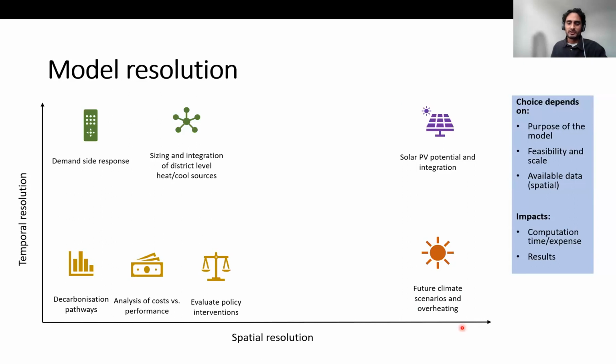They'd both be sensitive to building specific geometry. They'd be sensitive to the building orientation and also the surrounding context. So the shading would make a big impact for both of these 2. So these are just some choices you have to make as a modeler when doing this kind of investigation.